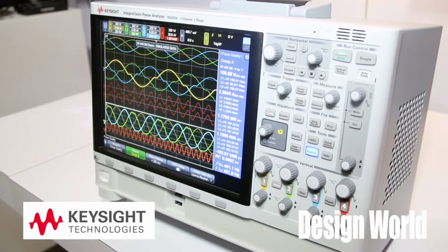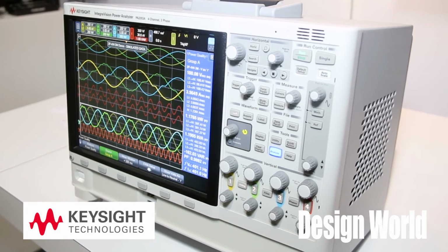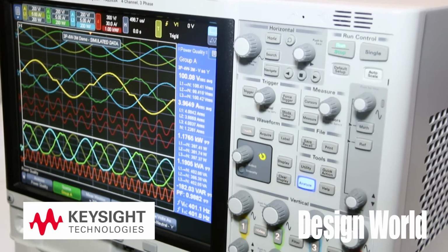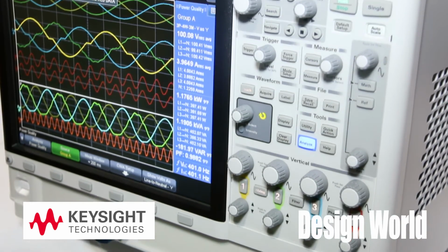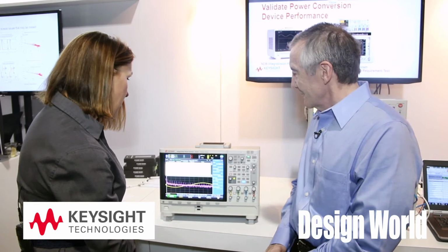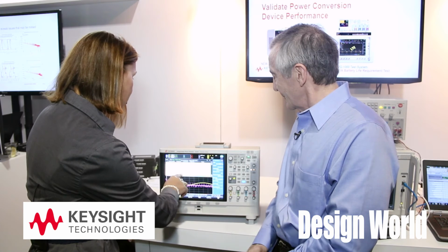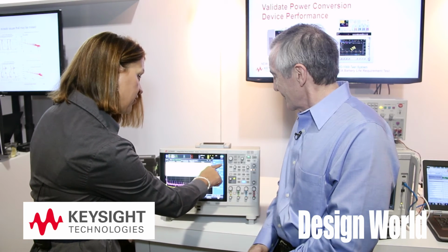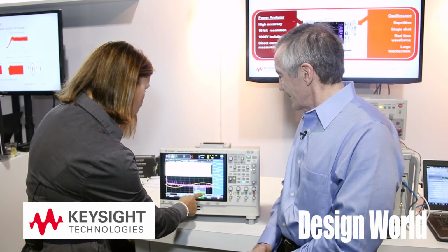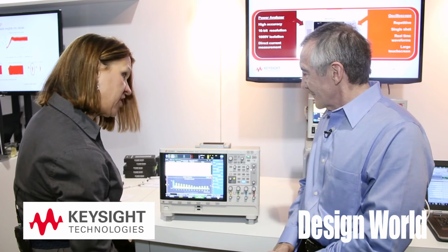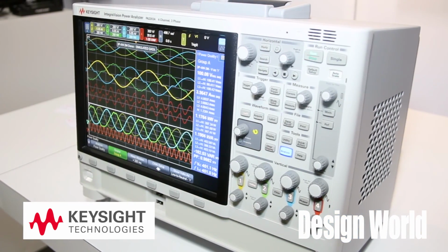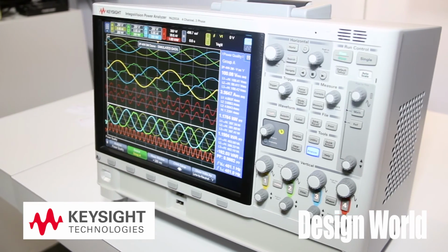And one more thing, there is other data you can look at, but mostly I want to show you now our harmonics. So you pick the signal. And what we do in the purple line is calculate the DFT, and here is all your harmonics information in the table, and total harmonic distortion nicely, quickly there. And also we can look at it in a bar chart. And what we also implemented is IEC standards, so you can see if your design is passing or failing the IEC standards.